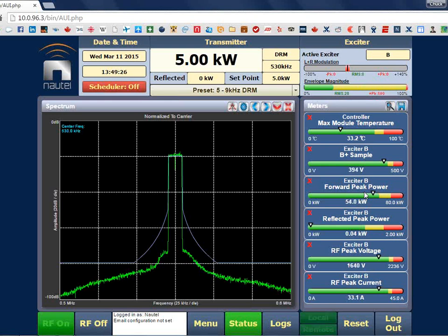How does it behave in strong AM fields from near stations? So I understand Oscar's question here. There have been situations where solid-state transmitters were located in sites in close proximity to other high-power AM sites, and you'd get cross-modulation where the power would come in the antenna system and go back out the antenna system after mixing in the output stage of the transmitter. Anything that we're doing here special that might aid that? I don't think there's anything special. So if you have that issue, you probably need to put some filters in and deal with those filters.